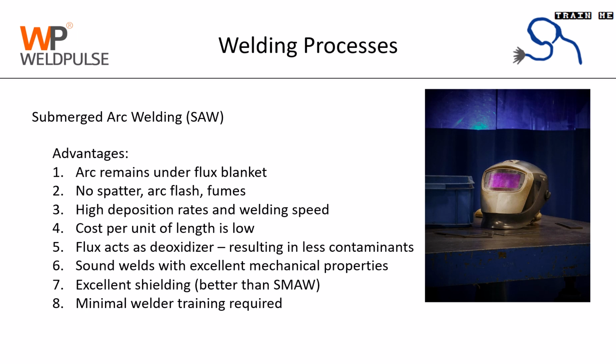Flux acts as a deoxidizer which results in low contaminants like oxygen, nitrogen and sulfur. This helps in obtaining very sound welds with excellent mechanical properties. Shielding in this process is way better than shielded metal arc welding. Also, this process requires minimal welder training.